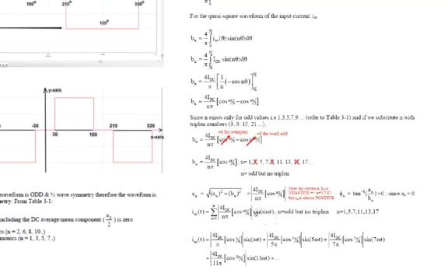If you write the Fourier series, you have a summation of n from 1 to infinity, 4 IDC over n pi cos n pi over 6 sine n omega t, but there is no triplet. It is odd but no triplet harmonic. So if you list down, it becomes 1, 5, 7, 11, 13, 17.